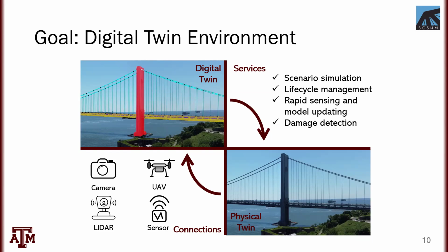To connect the physical twin to the digital twin, we're going to have connection devices. These are your UAVs, cameras, LiDAR, IoT sensors. And to connect the digital twin to the physical twin, we're going to have services. Those are essentially the benefits that the digital twin provides to the physical asset. So these include scenario simulation, lifecycle management, rapid sensing and model updating, damage detection.